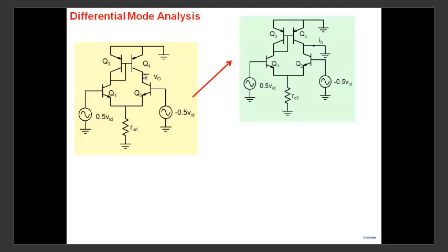What you do is you build a Norton's equivalent circuit at that particular point. So Norton's equivalent circuit would require you to find a Norton's current, IN. In order to find Norton's current, you always take that particular node, short it to ground, and find out how much current is flowing there. That gives you the Norton's current. And Norton's resistance, we know, is the resistance looking left, the overall resistance that you see there. The analysis becomes much simpler when you break it down into these two parts.